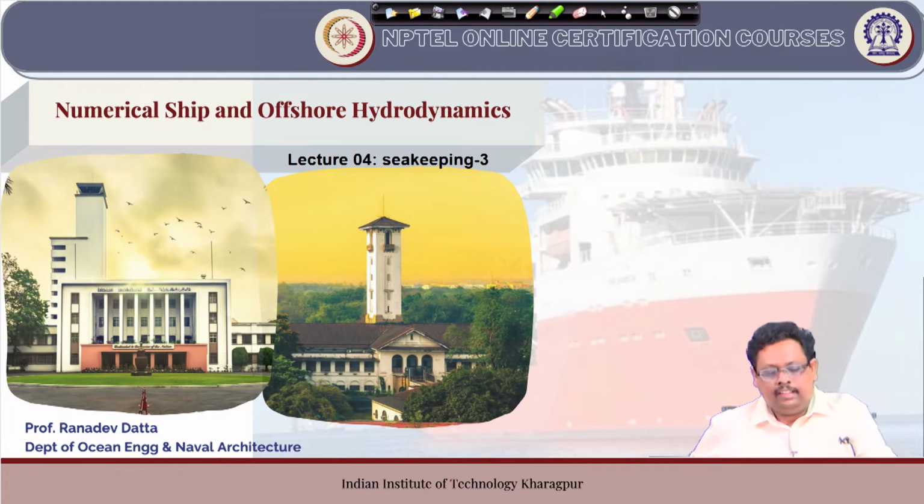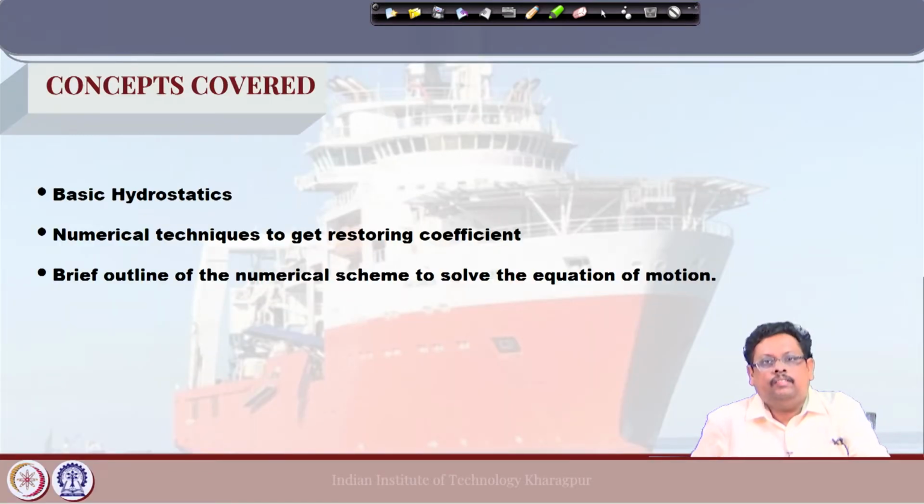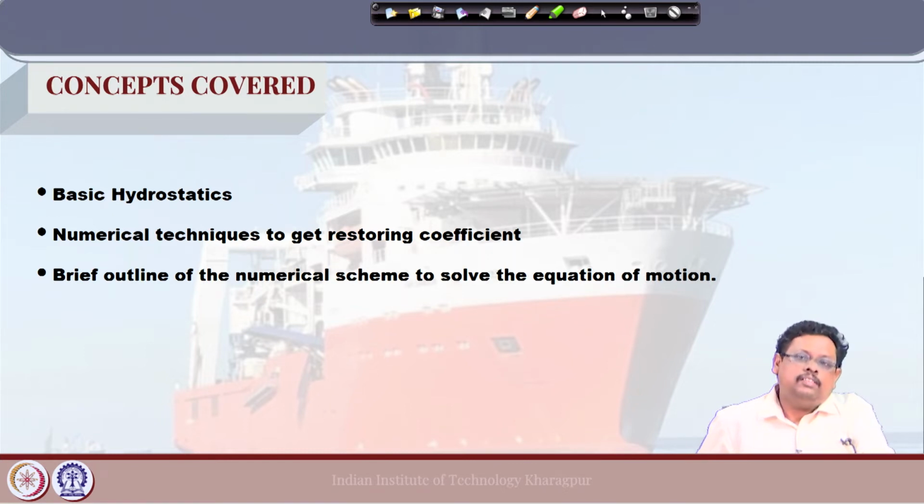In this lecture we are going to continue from our previous lecture, with some concepts of basic hydrostatics. Along with that, we are going to discuss how to calculate numerically the restoring coefficients, of which we have three that we need to calculate. We will also discuss a brief outline of how we are going to solve the equation of motion.